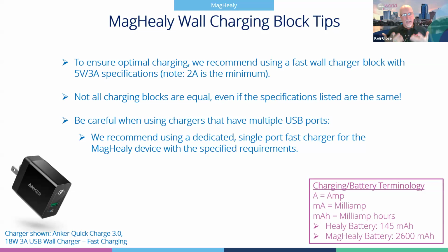One real important thing, as Jake said, when you've got a charging block with a lot of output ports, USB ports or plugins for charging different devices, the more inexpensive ones have limited circuitry inside. And so each of those output ports may be splitting the entire overall amp capability of that device.